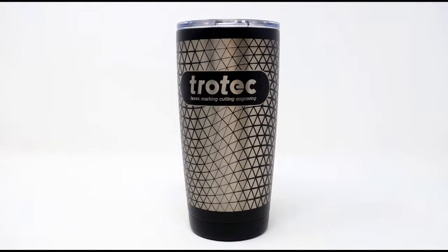But if it is a perfect cylinder, of course, you can engrave seamlessly. I've gone to the point of engraving a photograph where it was seamless, 360 degrees all the way around. Your math has to be really accurate on that one to get it just right. But the process is the same. Measure the diameter, take that diameter times pi, or 3.14, and then match your graphic to whatever that page size is.